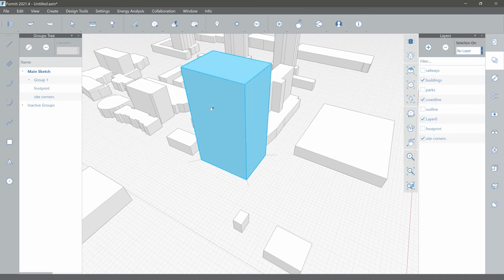We're just going to double click it to grab everything, and then press G, which will make a group, and then we'll call this sequence 1, I guess, S1 for short. And then let's make a new layer, call it S1, and then put this object on this layer. Now we can turn this on and off.